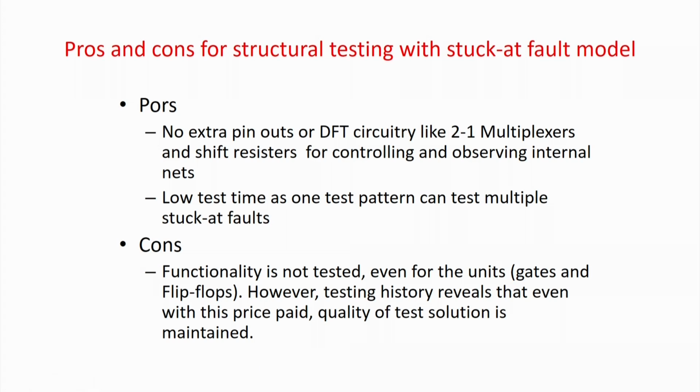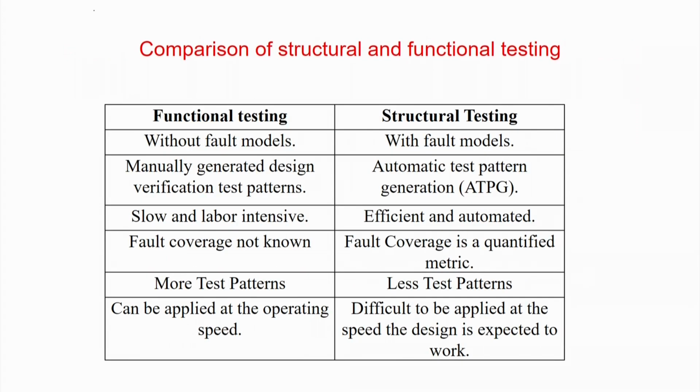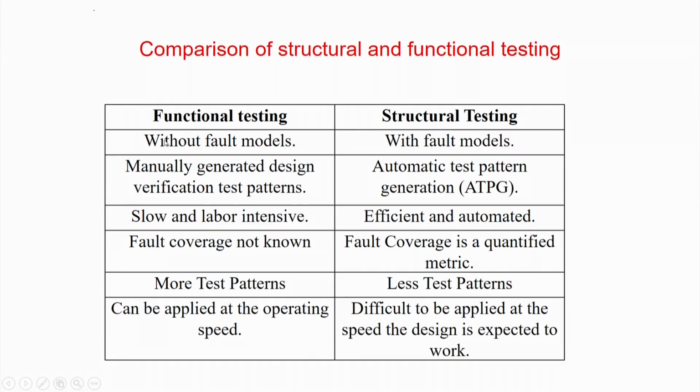So, therefore, this was a huge revolution in testing, that I can test at structural level with fault models, but still the compromise in quality is much less. So, this is the comparison. Functional test is without fault models, structural test is with fault models.